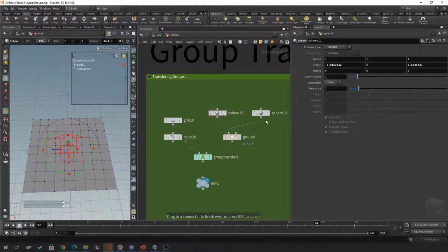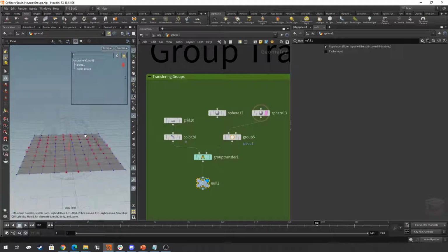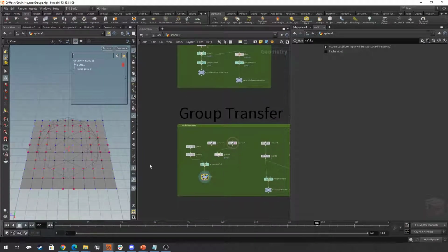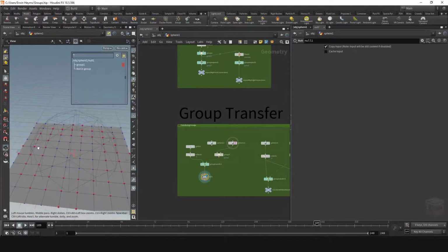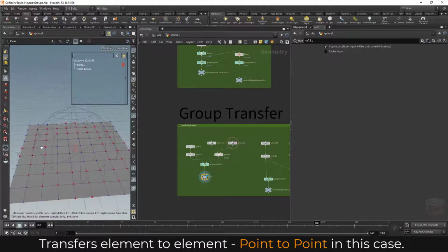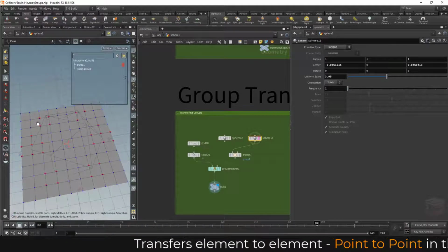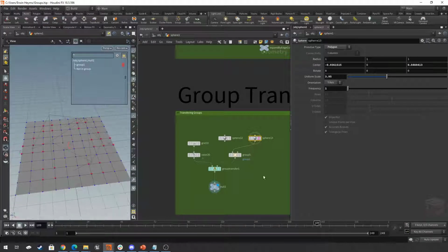Now if I plug in a bigger sphere here, you'll actually see that our selection gets a bit more hollow. And that's because our sphere is hollow. Unlike the volume selection that we could do before, this one isn't, and whenever our points get too far away from the points on this sphere, our selection is undone. So if I lower the amount of frequency on the sphere, you'll actually see that it only selects points near the points on the sphere. It doesn't select it based on the geometry of the sphere. For that we have to use different methods.